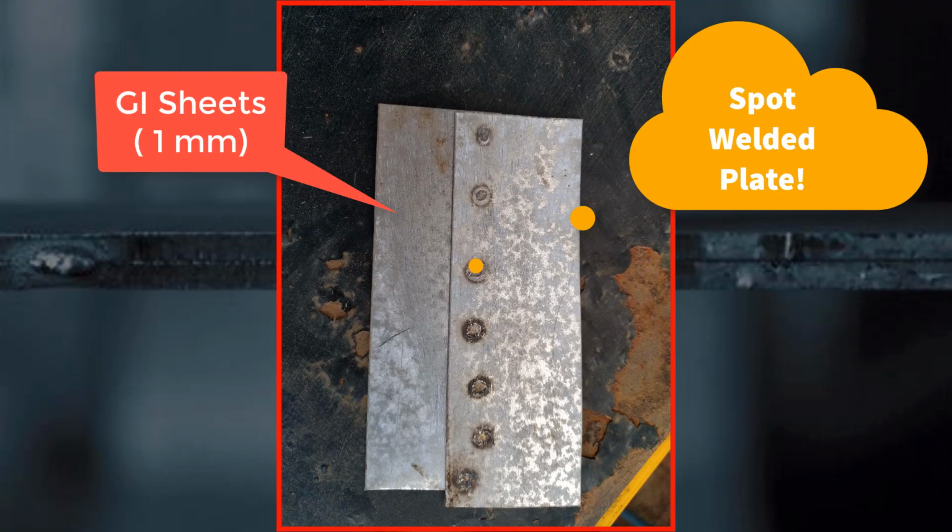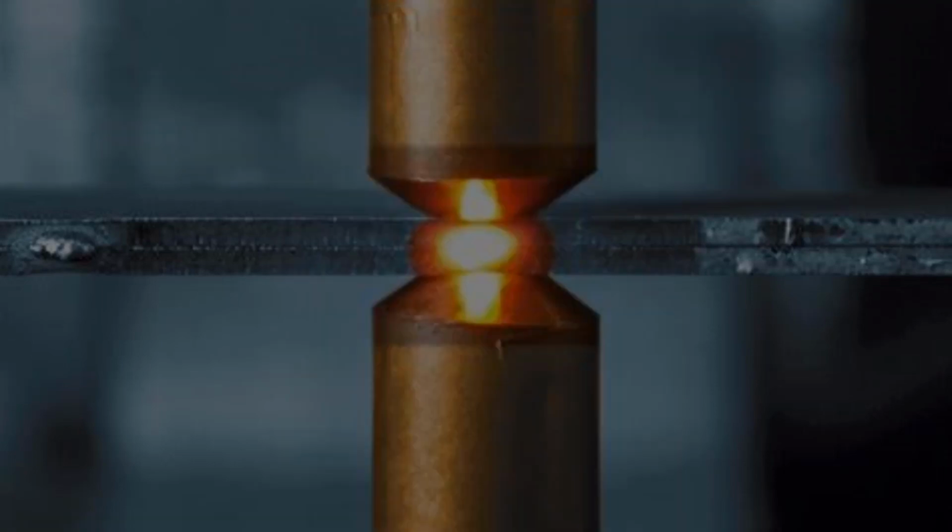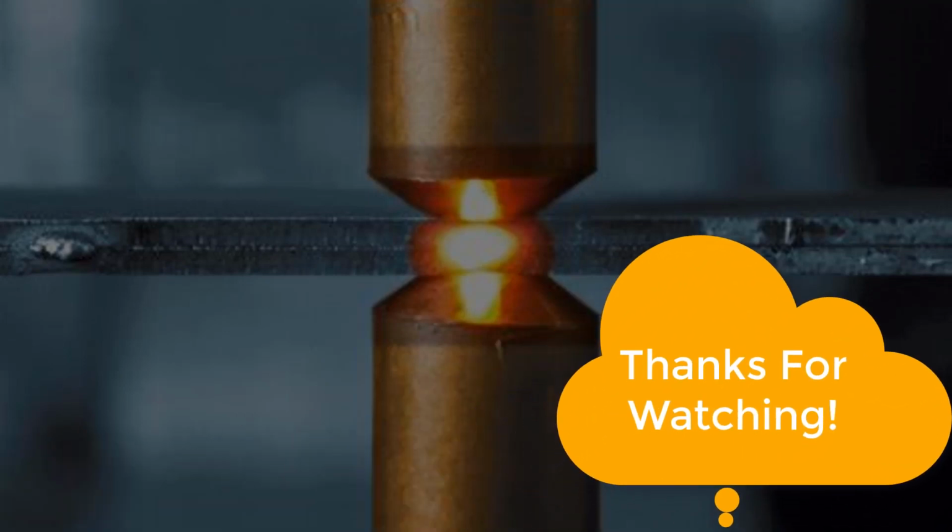Here galvanized iron sheets with a thickness of 1 mm are used, and by placing one sheet over another, the total thickness is set as 2 mm, right? According to that, we can set our thickness setting, and also the different settings of the cycles, right? So here, just by passing the electricity, we can make a permanent joint.